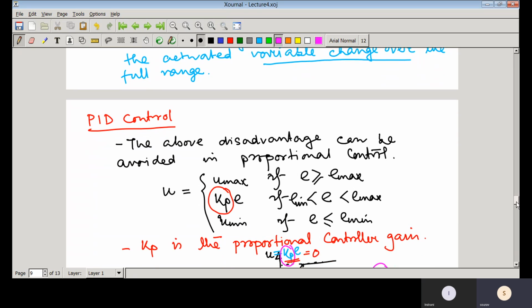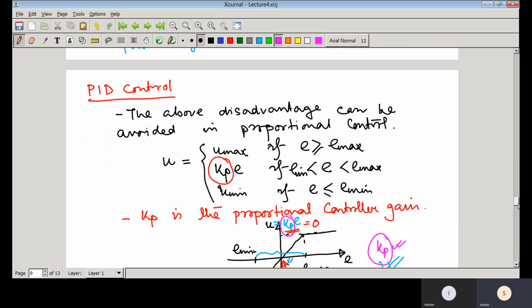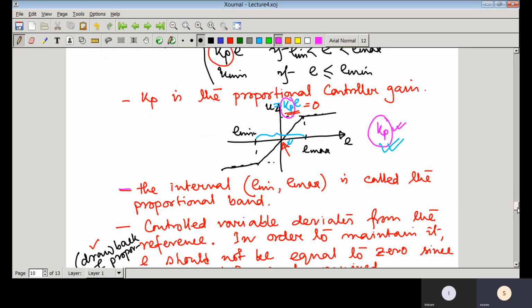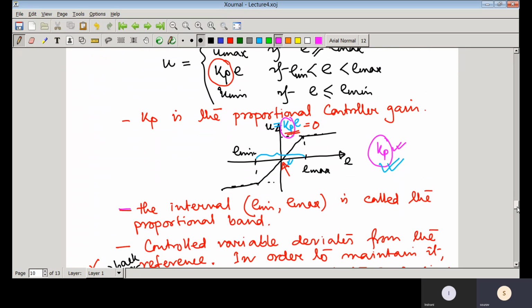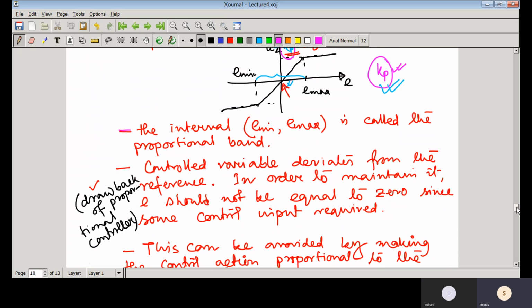Now in PID control, we have separately discussed the proportional controller, the derivative controller and the integral controller. And if we use them in various combinations like PI, PD, PID, you may ask if we can just use I or D controller, but you see there you have to use some gain, otherwise you cannot achieve the performance as well as stability.